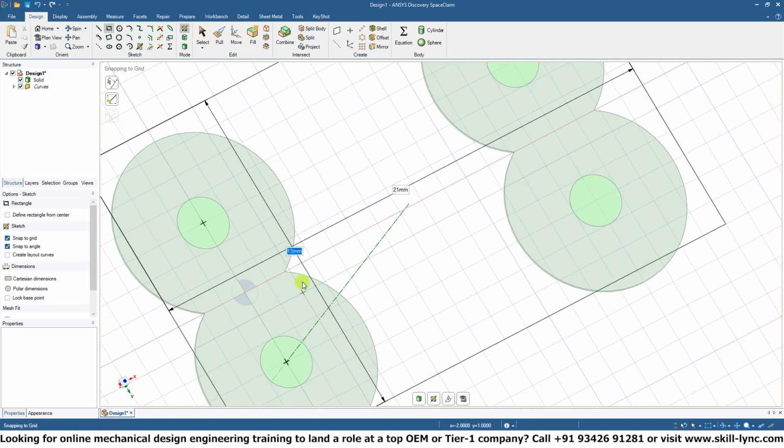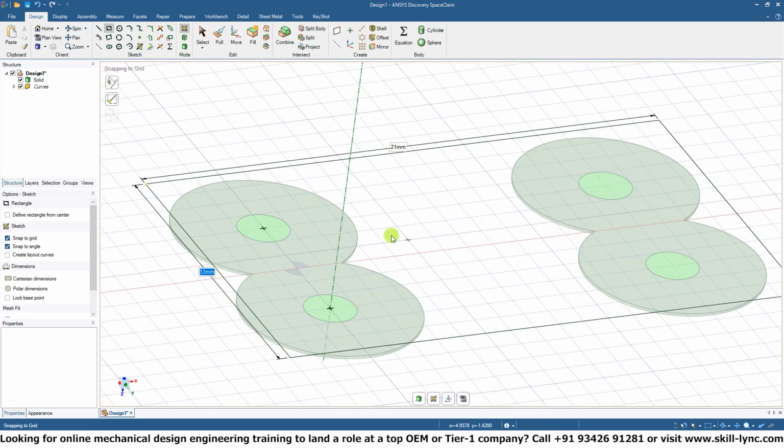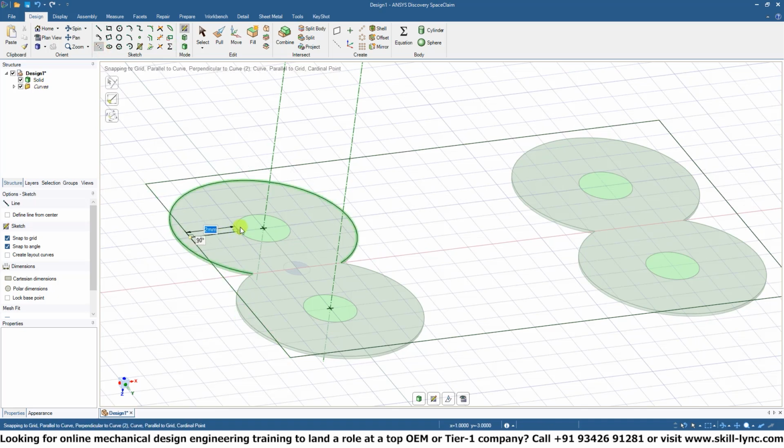However, this is not efficient as a brim, for the sole reason that over here the distance from the center or from the edge is much larger than this distance from here to the edge. So the weak point will actually be the distance from here to here. This distance that I'm drawing now is much shorter, is 2 millimeters rather than this distance, which is 4 millimeters.